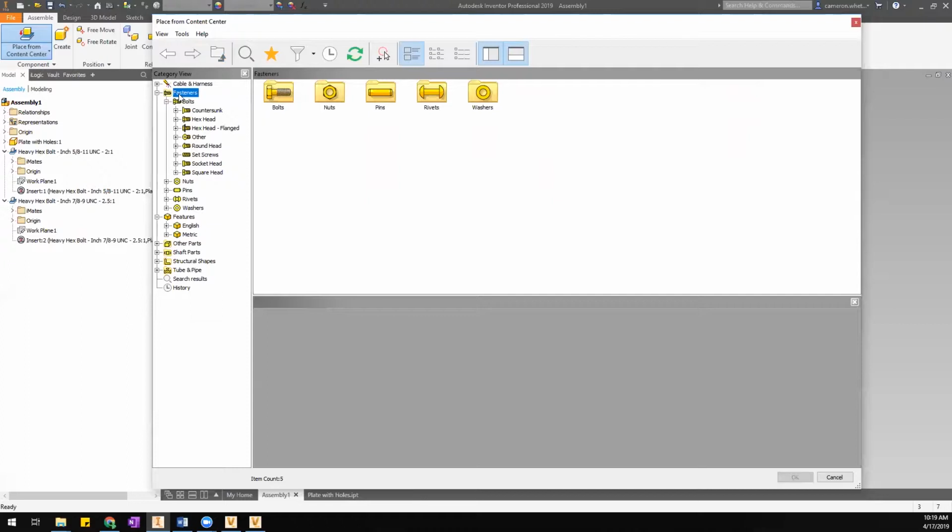One thing I will say on that while we're on the subject is if you have a part that really is an assembly, but you're okay having it represented as a single part file. For example, let's say you purchase a motor that, in real life, is an assembly, right? But if you're just buying it off the shelf as a single unit, it's basically just a part to you. And you could have an actual IPT file that represents that entire motor, and you could have those in your Content Center. That's fine, but they would have to actually be IPT files. You couldn't have IAM assembly files, right? So just keep that in mind.